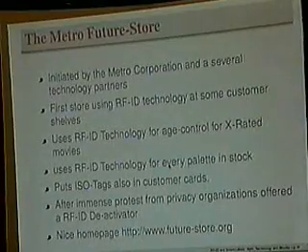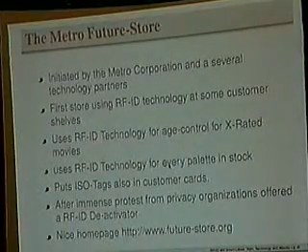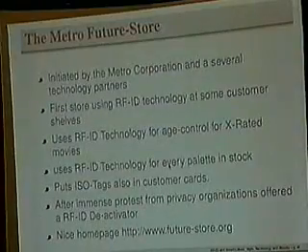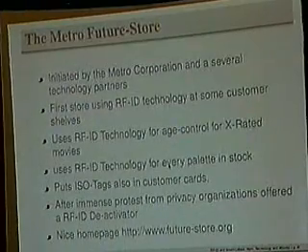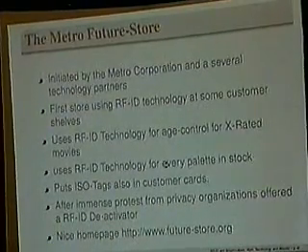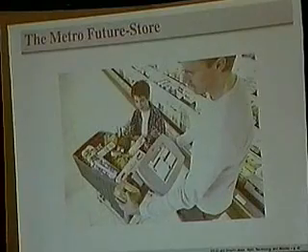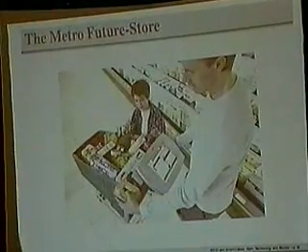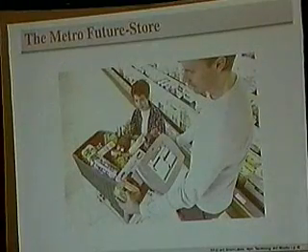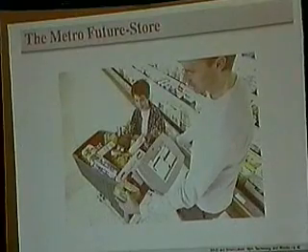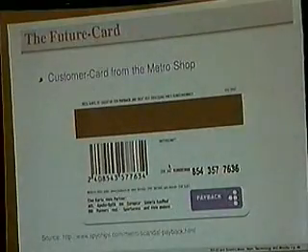I have here a couple of tags. So if I put one of these tags into the area of this field, I think it should be this size, the reader starts detecting the tag. It is reading the tag with its contents, and you have a hex and an ASCII editor. The administrative block is decoded at the top. You see here the tag ID, the unique number for anti-collision. You have the type of tag, the manufacturer ID, and you are able to manipulate it. You can use a hex editor.